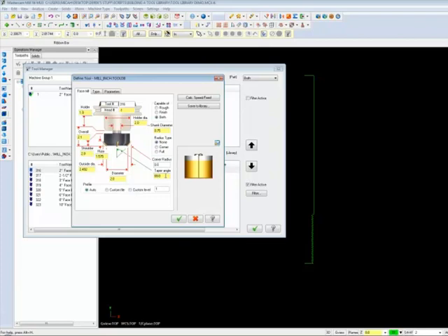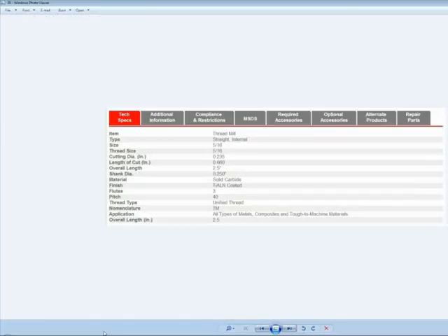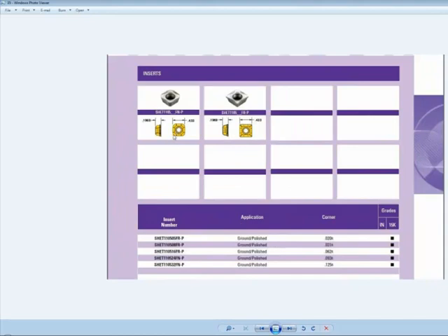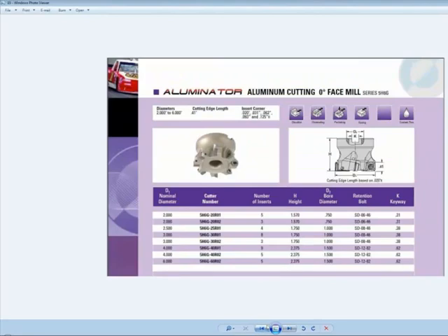It's actually confusing because a 0-degree taper is a square taper. Right. So when I set up the shell mills in the presentation, once you set the outside diameter at 2 inches, these are 0-degree inserts in the shell mill. Right, as opposed to 45, which would be different. Or how we're looking at your second insert there, it would be set at 45 degrees. Sometimes they're set at a different rake by whoever the manufacturer is. But yeah, the definite.